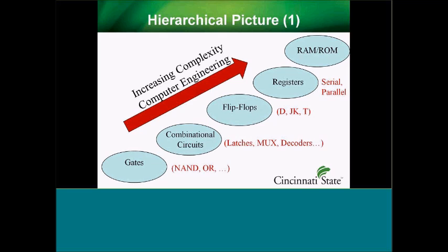A PLD, for instance, is a programmable logic device. That's the device. Then we talk about flip-flops, where you're combining latches into the three main types of flip-flops: the D, the JK, and the T flops. Then you take numbers of flip-flops and put them together and you build a register. Then we talk about serial and parallel registers, and then you take all your registers and put those together and you've got memory of some form.